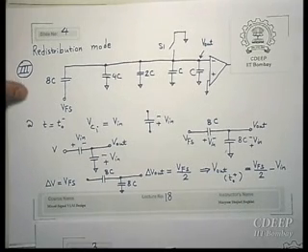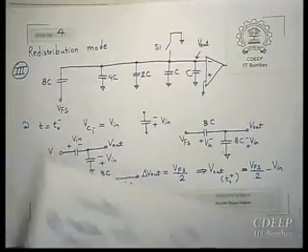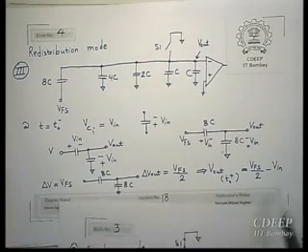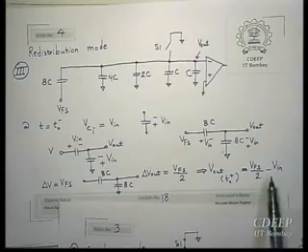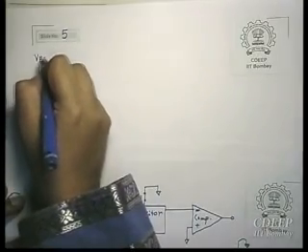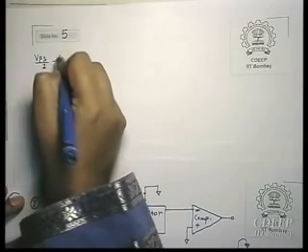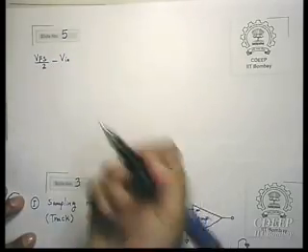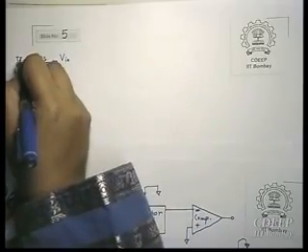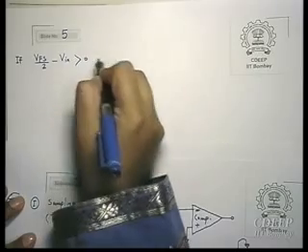Okay, so is it clear? So now what will happen in this case? This voltage is given to the comparator. So what it does, it is comparing V full scale by 2 minus V in. So now the input of the comparator has V full scale by 2 minus V in. There are two cases, either this is positive or it is negative. If V full scale by 2 minus V in is positive,